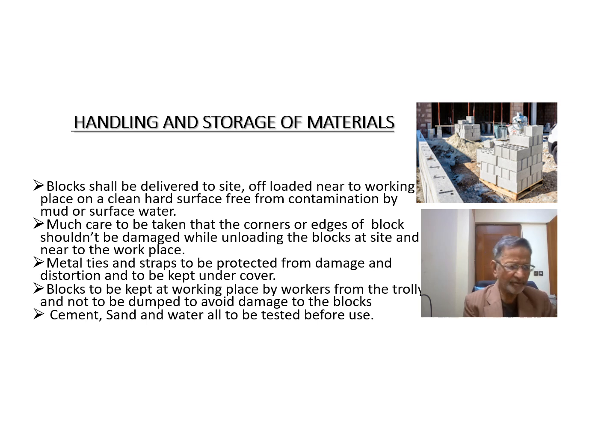Blocks should not be unloaded by the wheelbarrows or trolleys because they will damage the blocks, and blocks with damaged corners or broken edges are not to be used in masonry. Broken bricks also are not to be used in masonry. Blocks shall be delivered to the site and offloaded just near to the site on a clean, hard and smooth surface.